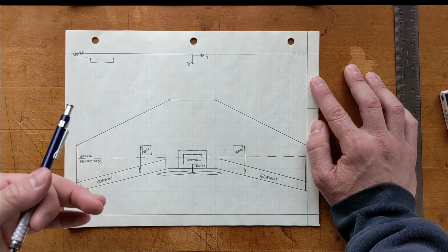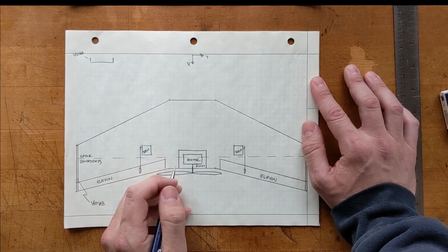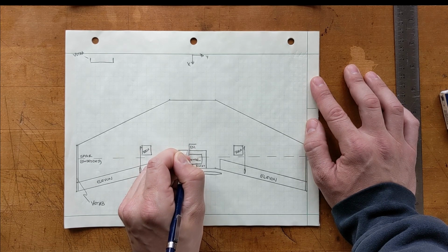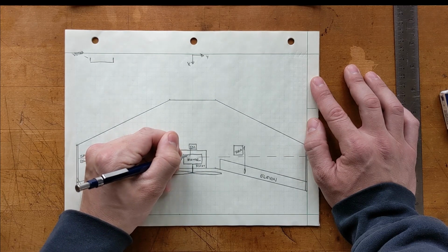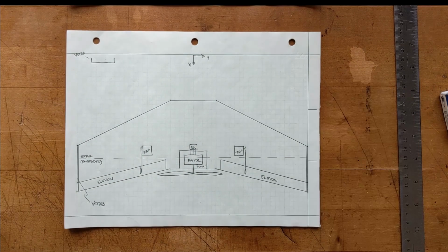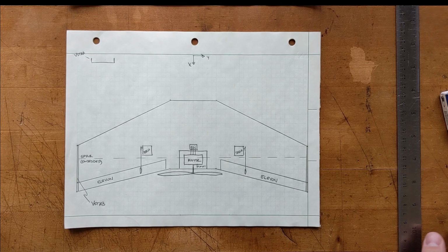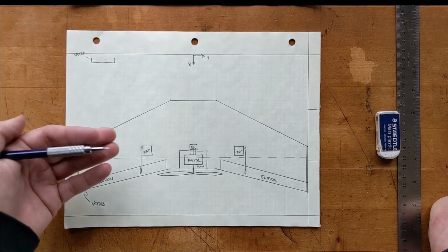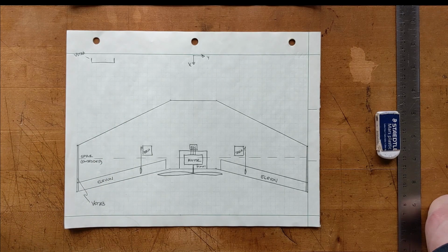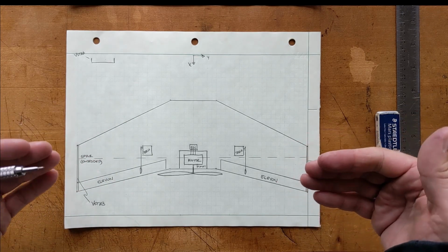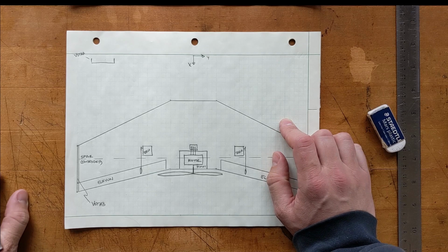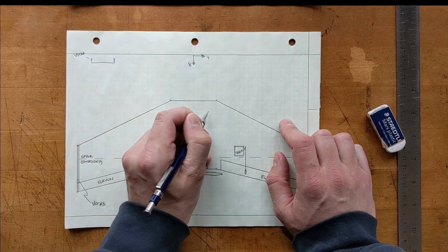Now we're going to need a way to power and control that motor. Well, let's give it an ESC, electronic speed controller. We're also going to need a power supply, a way to store all that. That's going to be a battery. And we're going to bias that towards the front of the aircraft. We'll put it on the bottom side for now. And that's going to be to move the CG, the center of gravity of the aircraft, forward. And we'll need that for stability reasons that we'll talk about more in the future. So let's say, I don't know, somewhere like this.